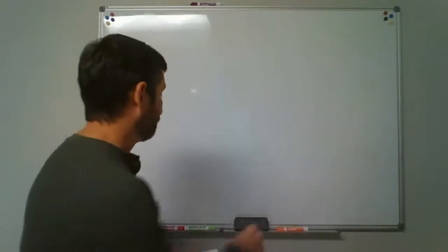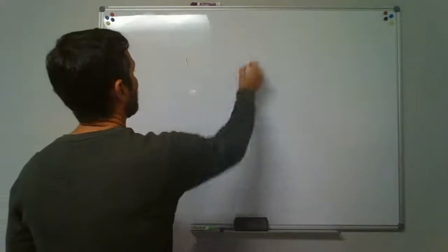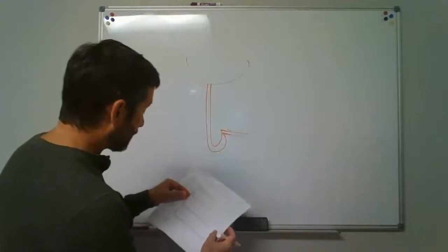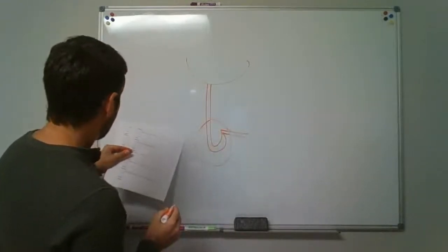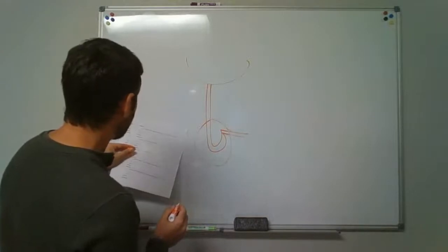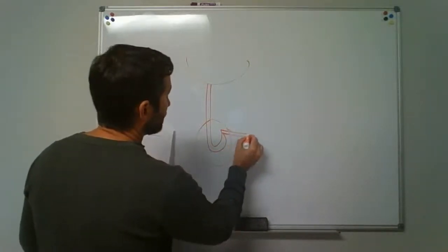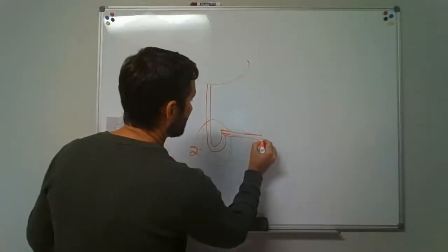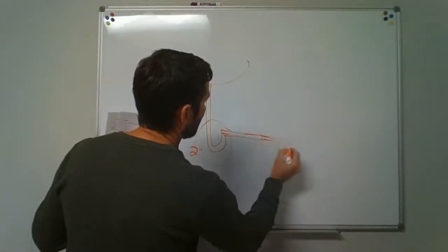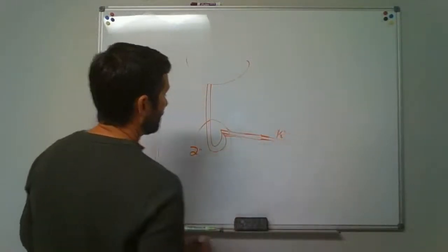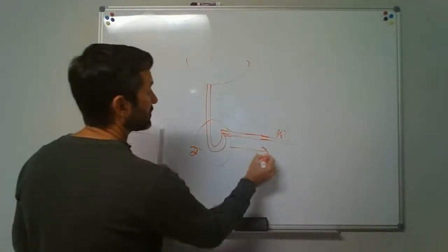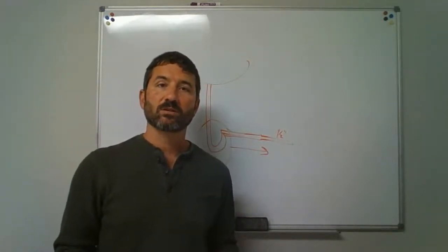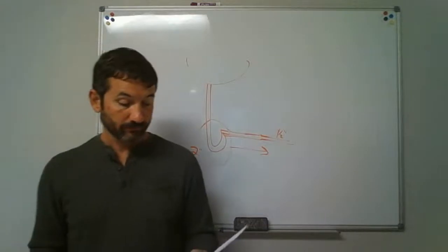The fixture trap. Let's look at that. Fixture trap. All right, what fixture we got? Let's say a lavatory. Let's come down and put a fixture trap on that. Can that fixture trap be larger than the drain pipe it goes into? So we have that coming out as a 2-inch trap and then reduce it down to a 1.5-inch pipe. Is that allowed? Can we reduce in the direction of flow? In Chapter 7, we talked that you cannot reduce in the direction of flow.